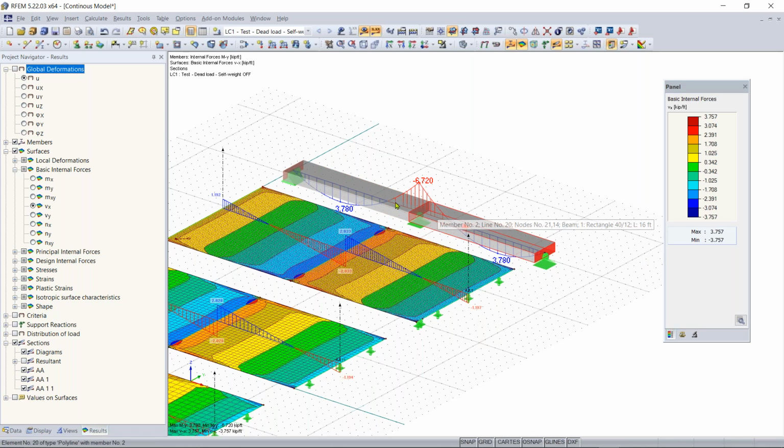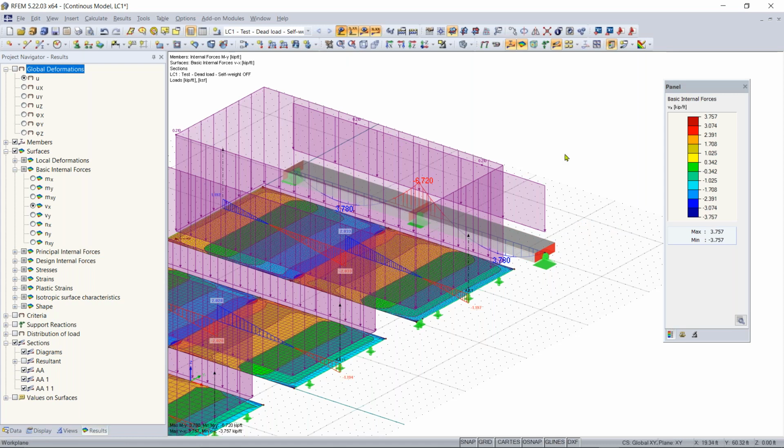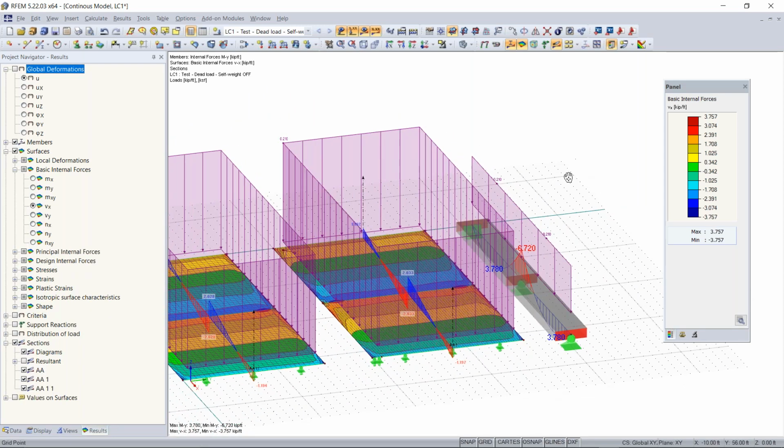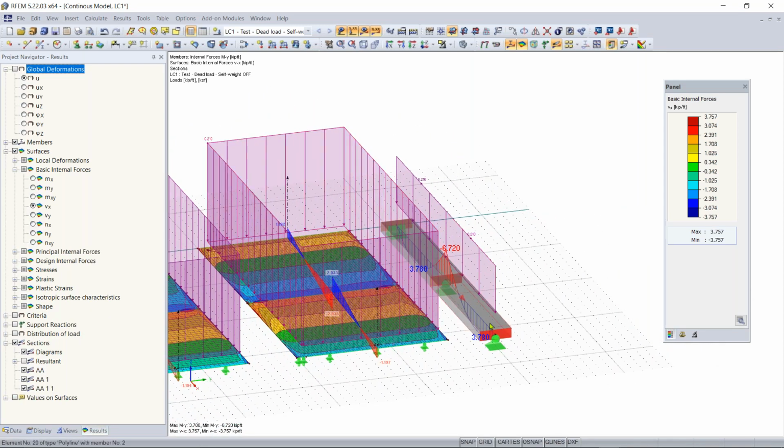So the weight of the beam, or the self-weight, is superimposed with the loads that you apply to it. So if I had self-weight turned on, you could visualize that as a uniform load applied to this member on top of this load that I applied. So the shear and bending moments would be higher. I think that answers your question.